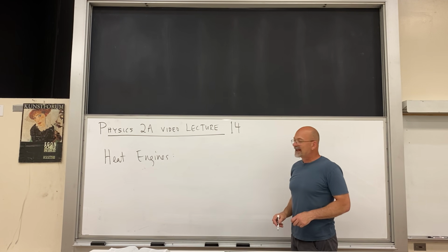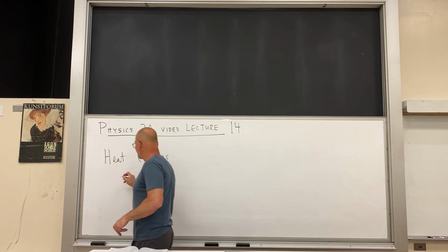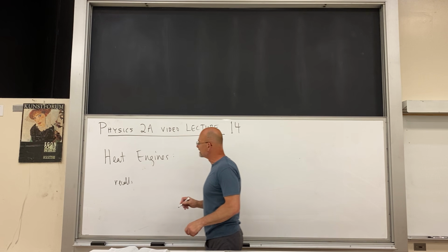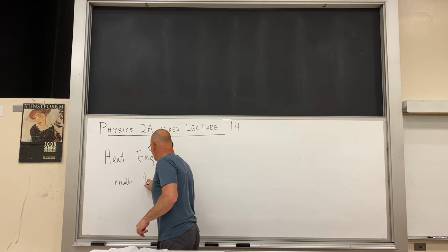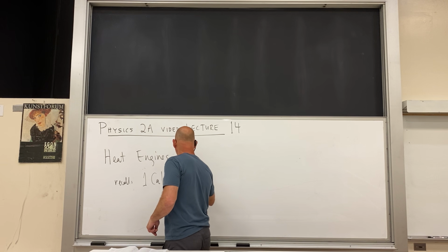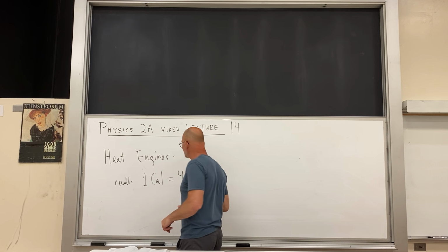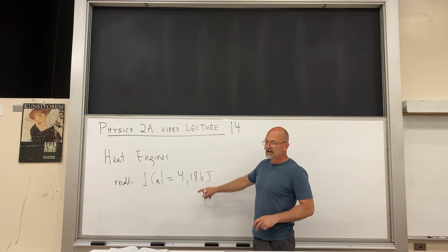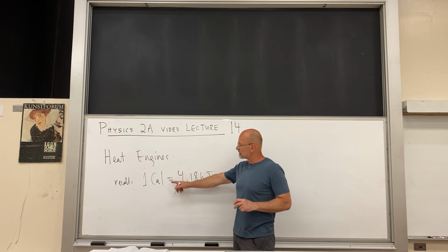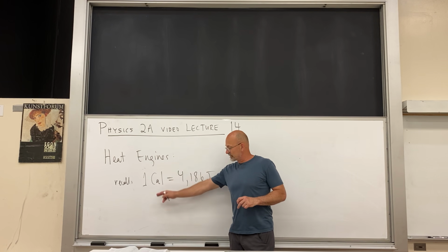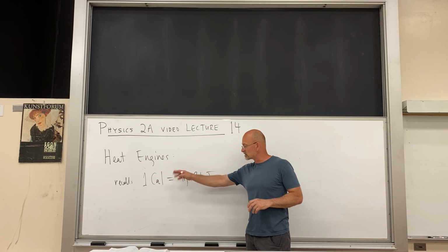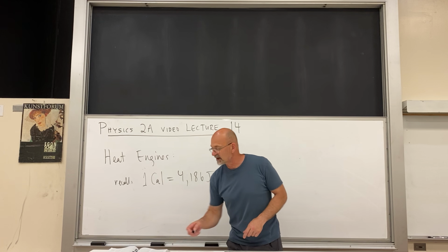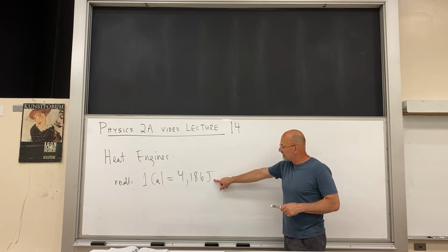We know that there's the mechanical equivalent of heat that says that 1 calorie equals 4,186 joules. This is a measure of changing the temperature of water, and this is mechanical. At this stage, once you know about the mechanical equivalent of heat, you can actually dispense with the calorie, but I'd like to keep it there just to remind us of its original thermal definition and content.